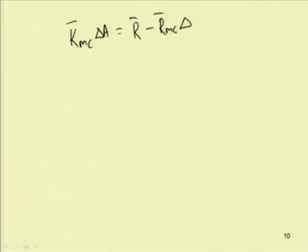So, we will have this equation, that is K m c bar delta A equal to R bar m c into delta W. So, this is increment in the amplitude and this is increment in the frequency. Where this K m c bar can be written, as we are applying this Galerkin method over a cycle, so this is 0 to 2 pi.